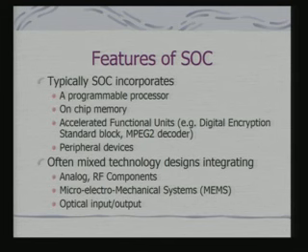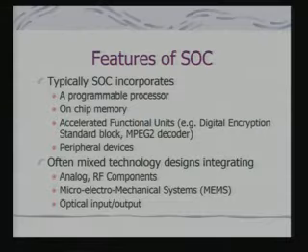What are the features of these SoCs? Typically, our SoC incorporates a programmable processor, on-chip memory, and some additional functional units which are more application specific, like a digital encryption standard block or MPEG decoder. This we call accelerated functional units. On top of that, there would be peripheral devices. But this is a very typical SoC configuration. Along with it, we may expect other components as well.